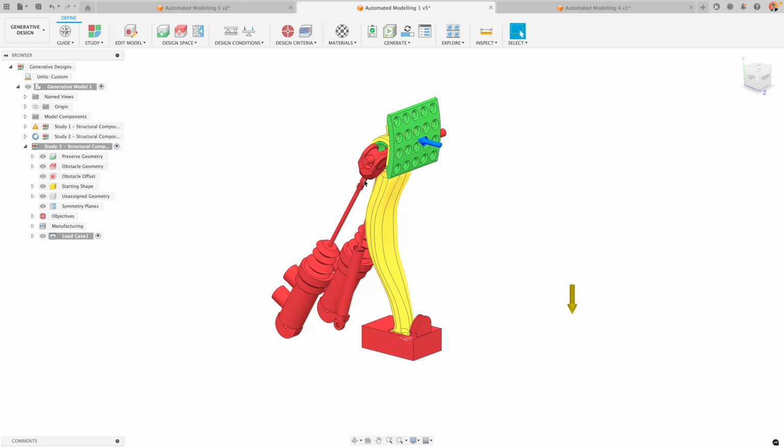When we do this, it'll go yellow, and we can then run our generative design study, and the result we'll get back will be the same design that we have put in, but only optimizing for mass and removing unnecessary material. Now, whilst this does reduce the creative production, generative design can't account for everything. So sometimes you need to apply your own design decisions and allow it to only optimize what you want it to, reducing the amount of time that you have to spend sifting through different design iterations that the tool gives you.